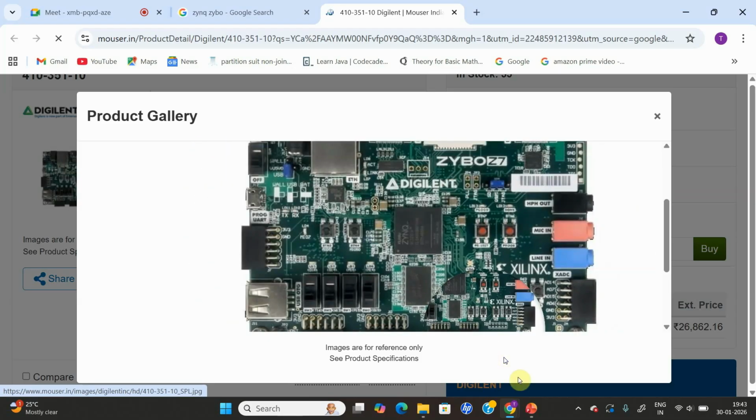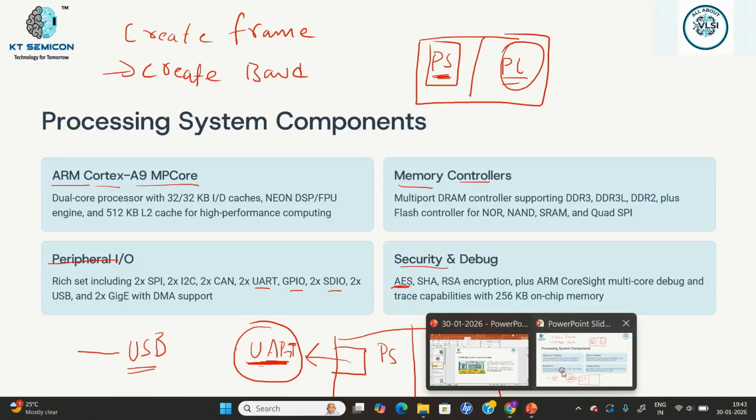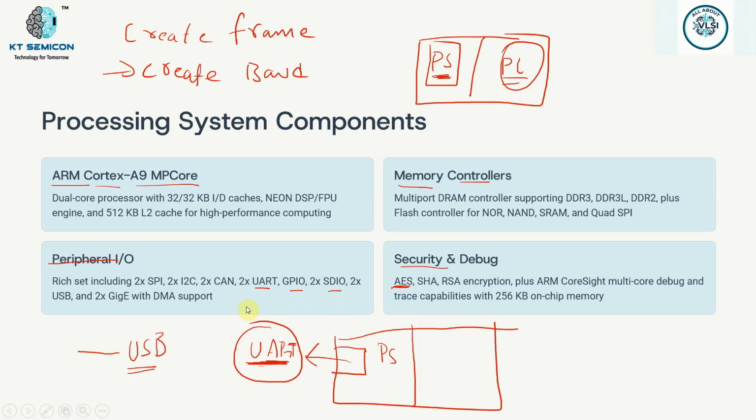So I have my processor over here, right? My processor is going to have something known as a UART controller, which is going to receive that particular UART frame, and it can also filter that UART frame. Whatever data you are going to receive via the UART frames, it can basically receive and understand those. So my processor has that capability using this UART interface.